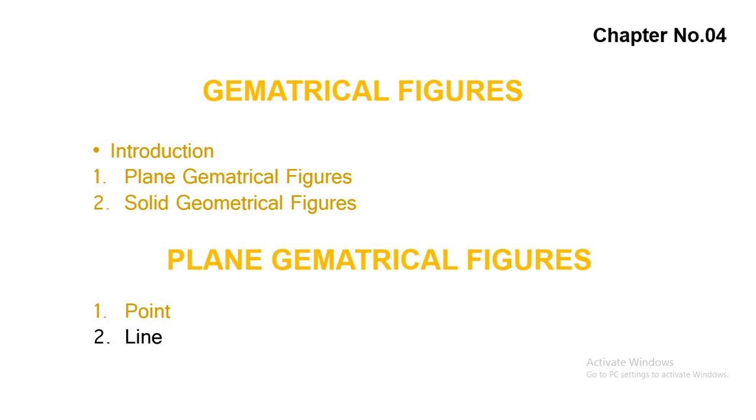Dark lines are drawn with an HB or H pencil, while light lines are drawn with a 3H or 4H pencil. The drawing is first drawn with a lightweight pencil and later completed with the heavyweight pencil.